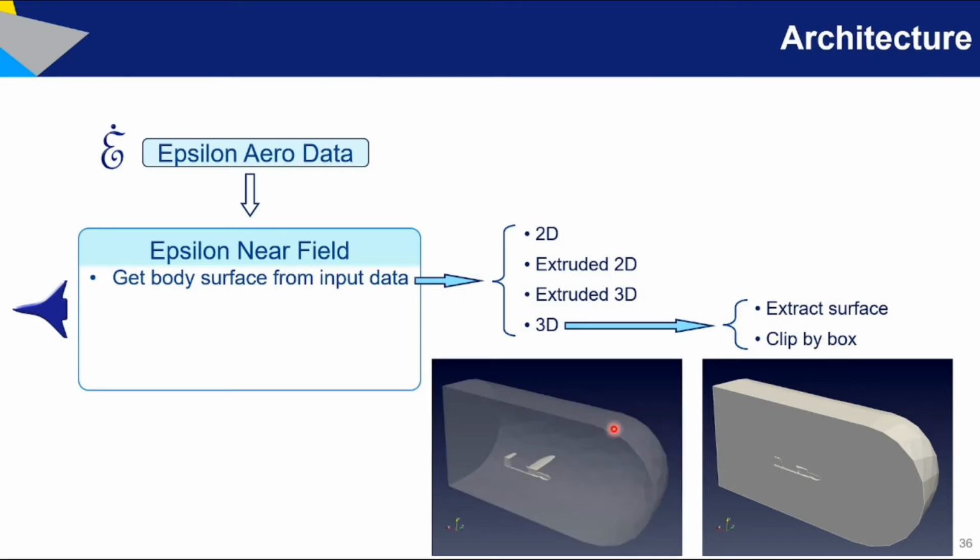So this shows you better the idea. We start from the volumetric domain. We retain only the shell that contains the surface. And the idea is to retain just the aircraft body. And this is achieved with a clip by box. Basically, it generates a sort of box that will help you to clip and retain everything that is inside the box.